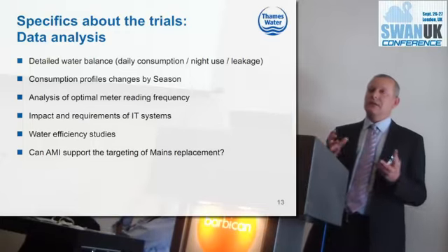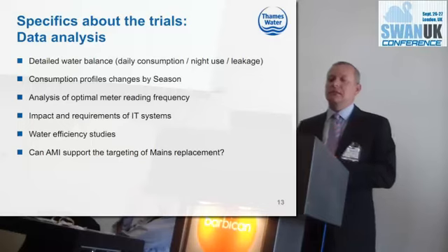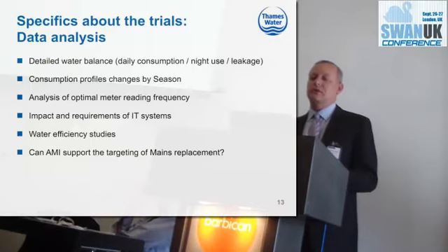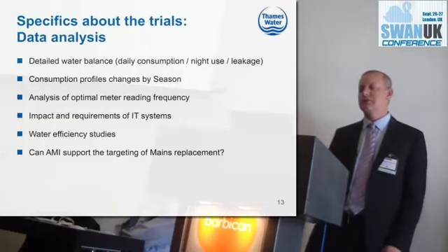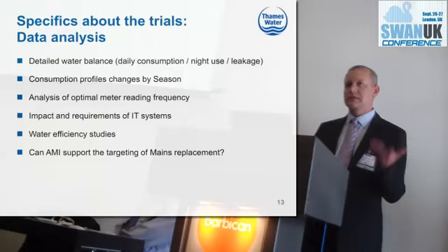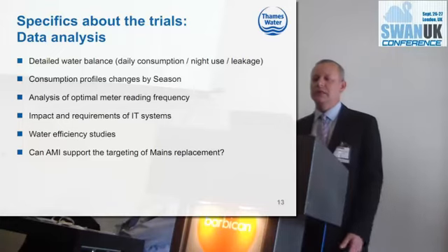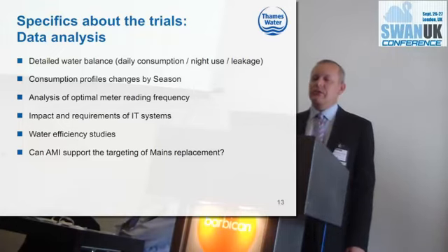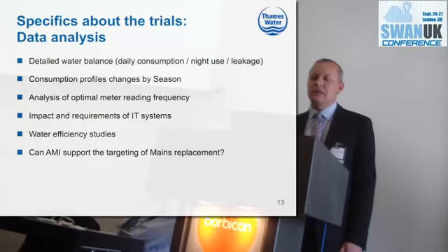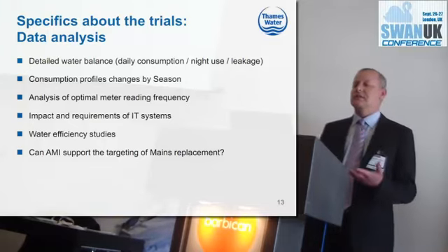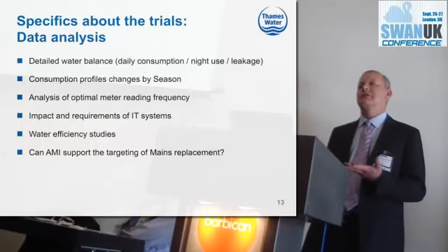The other part that we are analyzing is the data, which, as I mentioned before, will give us a detailed water balance with daily consumption, night use, leakage levels, customer side and network side. I mentioned before the consumption profiles: how do they change through the seasons? What is the optimal meter reading frequency that we need?